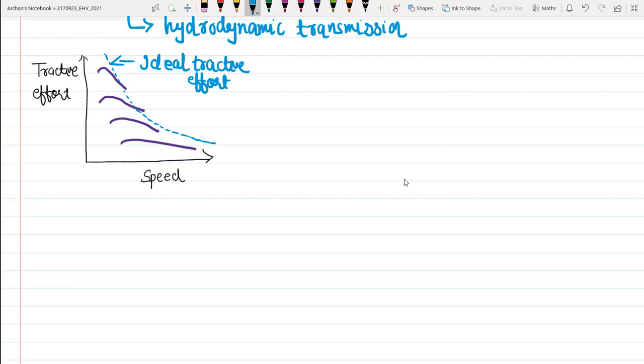Okay, so here in the first iteration, the gear ratio between the highest and the lowest gear may be selected in such a way that the engine can operate in the same speed range for all the gears. This approach will benefit the fuel economy and performance of the vehicle.